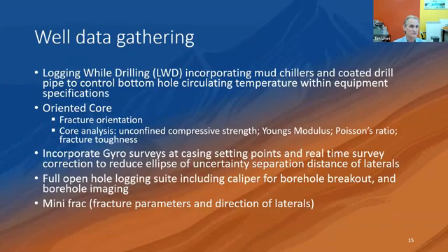I think that this is when you're actually drilling the wells. So in our particular case, we're drilling fairly hot, about 270 centigrade. And so the LWD equipment, which is vital because we're directionally drilling, we therefore need to make sure that the equipment doesn't ever see a temperature above 175 centigrade, at least for most of the equipment on the market. That's the electronics fry temperature, after which you've just got a lump of metal that's millions of pounds worth that you've lost. So you do need to keep this equipment as cold as possible so it can continue to operate.